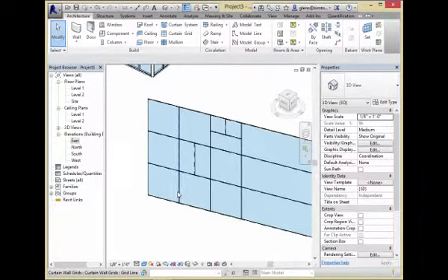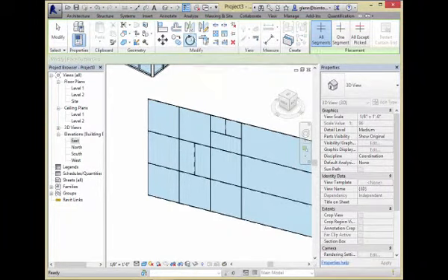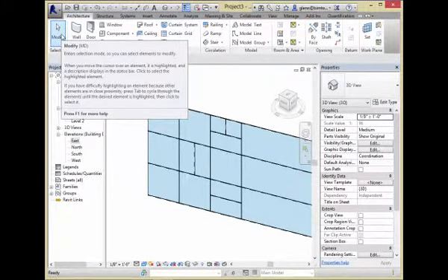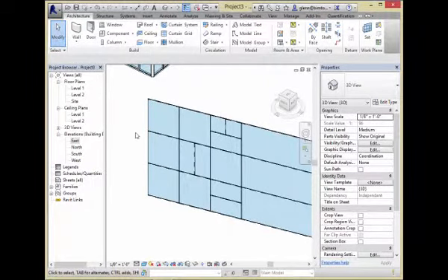So let's zoom on in there. Again, what I'm doing is just under the curtain grid, either all segments that'll cut across the entire surface, or one segment that'll just sort of split the difference. It'll only do a little piece of it. Okay? And I can start creating these very custom patterns. Now the cool thing is, okay, it's looking pretty much like a curtain wall. It's getting close anyway. We might still have to add some mullions, still just a bunch of broken up glass.